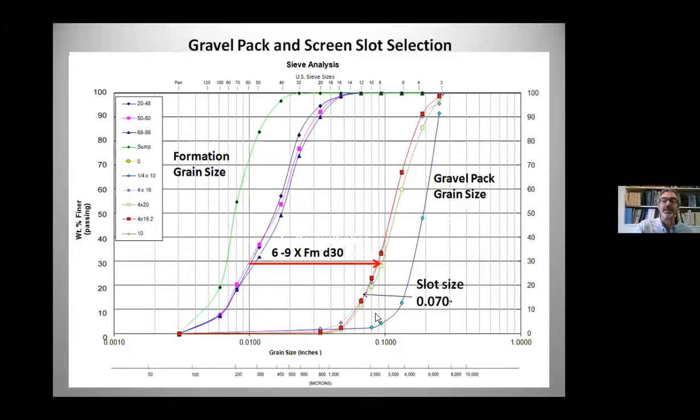Okay, so basically what we've done here: I was discussing some of the qualities of the filter packs we were looking for, but a high silica content is very, very important because we know this is a very stable element. For the same reason that it's the most common element in the Earth's crust, we'd like to have it in our filter pack.